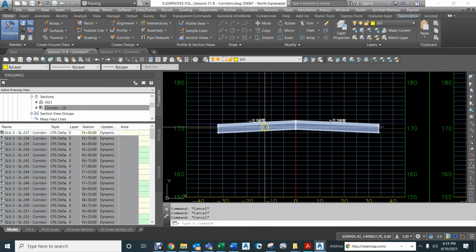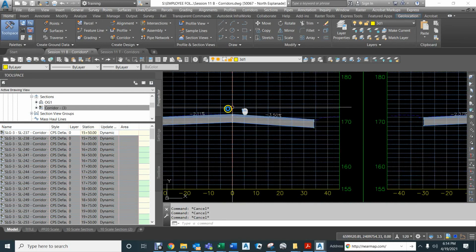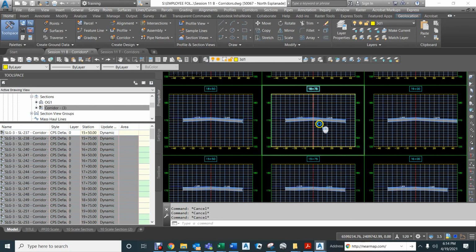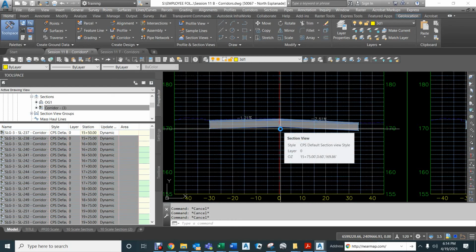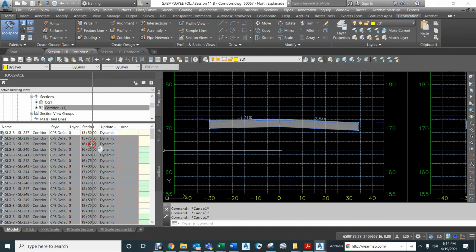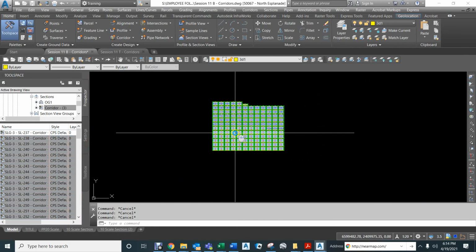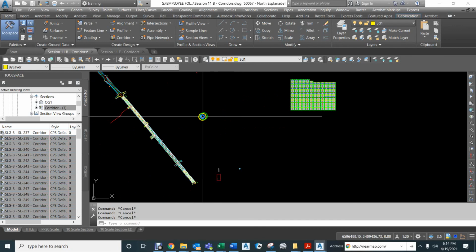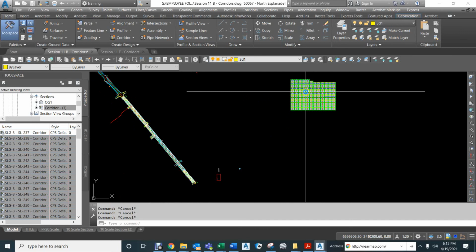So now that it adjusted, 2.56, 2.19, 2.17, we can see what that roadway now looks like. The right-hand side is 3.5, and the left side is 2.11, so on and so forth. So now we have something to work with, and now we can start making appropriate decisions. You need to really have all three pieces of a roadway to figure out if the roadway is ample or not. So you need to have the alignment, you need to have the profile, and you need to have the cross sections, and they need to show all these components.